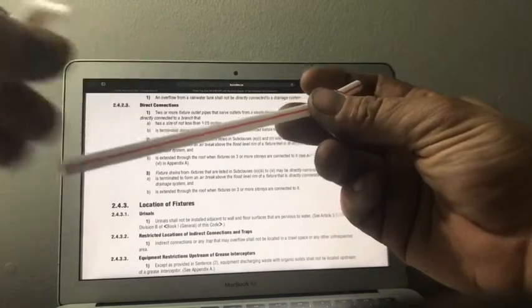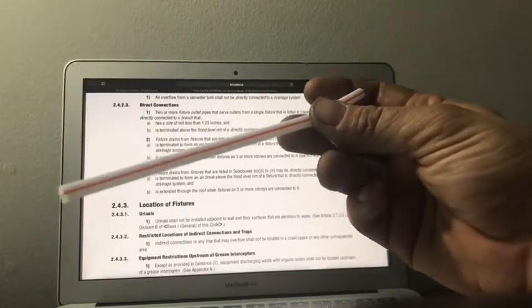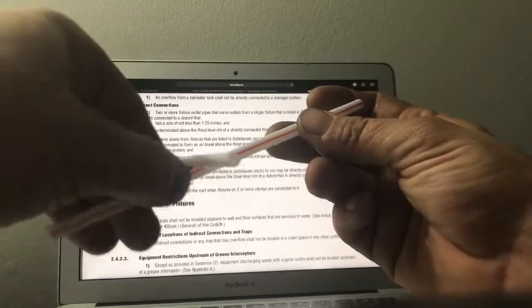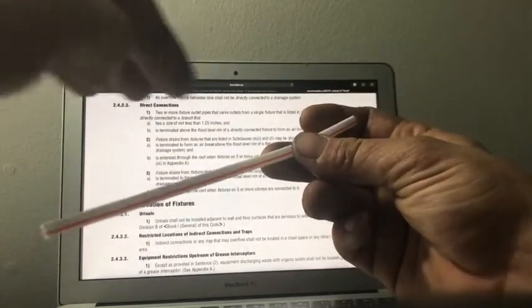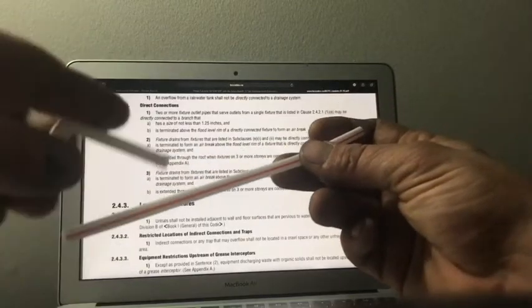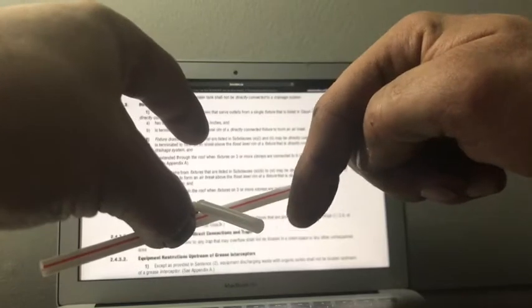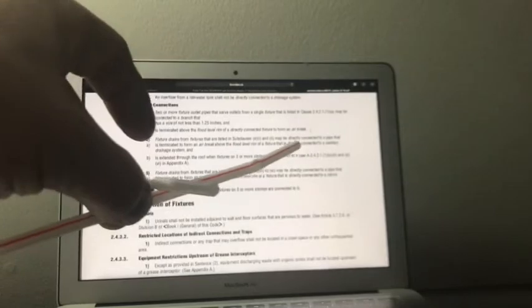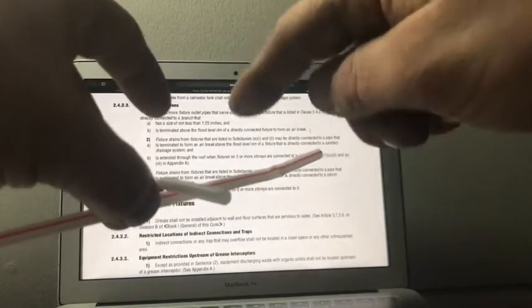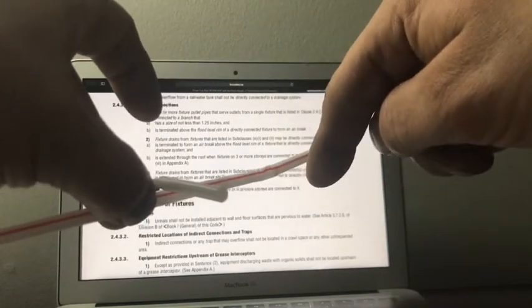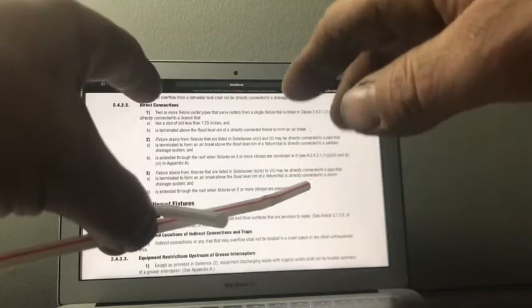That's where you have a 1.25 inch DWV serving as a branch, well, the main line for all your condensates, to put it in English, and then just branch here. A little T goes off there, off your line, picks up a unit. Pretty traditionally, let's say it's a furnace in an office space kind of warehouse. Then you have another 3/4 T, another furnace in the office space warehouse, or whatever you want to have heating or cooling